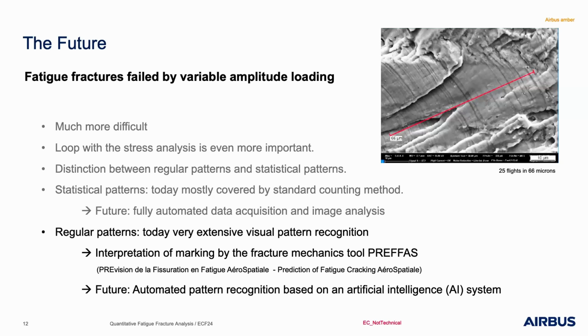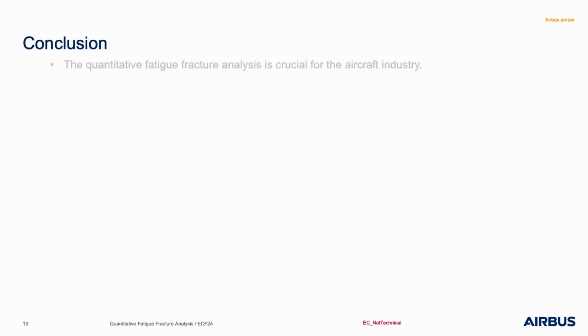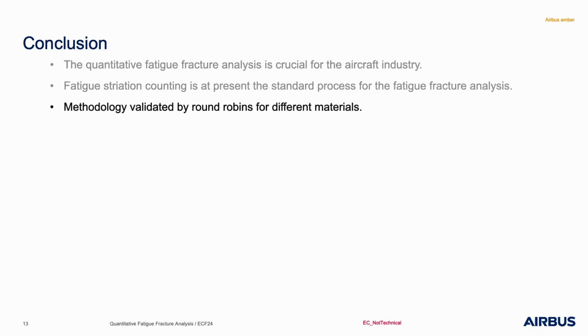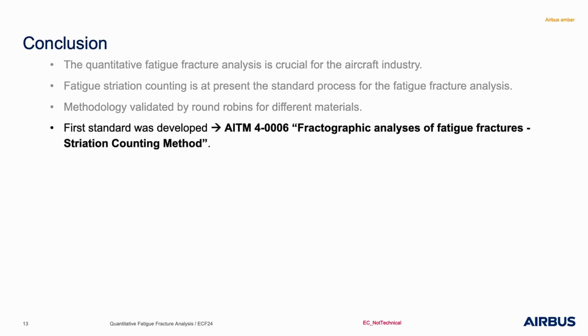So to conclude, the quantitative fracture analysis is really crucial for us in the Airbus aircraft industry. The fatigue striation counting is at present the standard process, and I think this will not change so fast. And the methodology is validated by round robins for different materials.